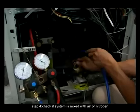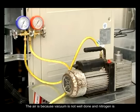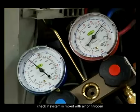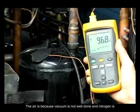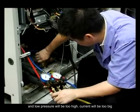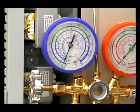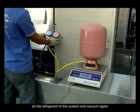Step 4. Check if the system is mixed with air or nitrogen. The air is because vacuum is not well done, and nitrogen is because the pressure test is directly done to the ball valve. If the system is mixed with air or nitrogen, the phenomenon is that high pressure and low pressure will be too high. Current will be too big, the compressor has abnormal noise, and the pointer of the pressure gauge will shake. If there is such a phenomenon, please discharge all the refrigerant of the system and vacuum again.